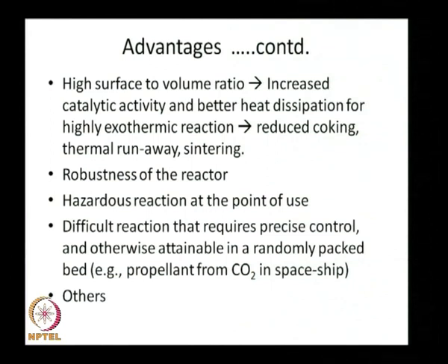Again, think of a probe volume. If you load your catalyst randomly in some places, as the two streams enter a randomly packed bed of catalyst, they encounter the catalyst on the way. In some volume, they find the catalyst loading is much higher, and in some volume much lower.